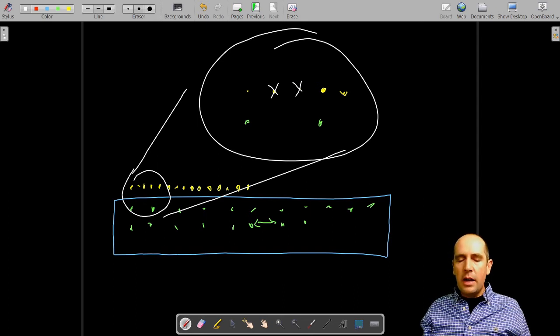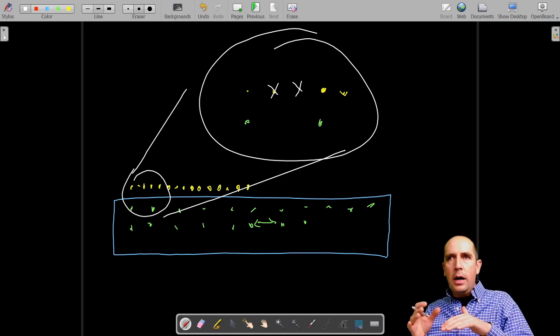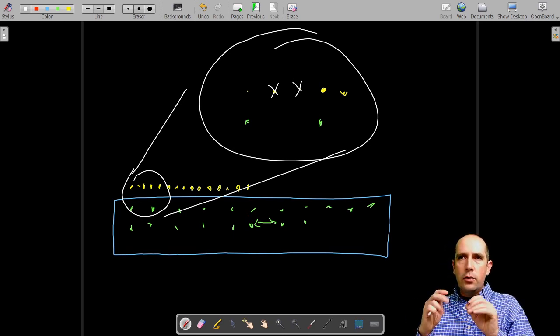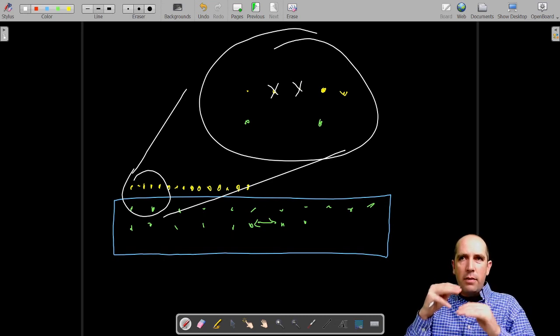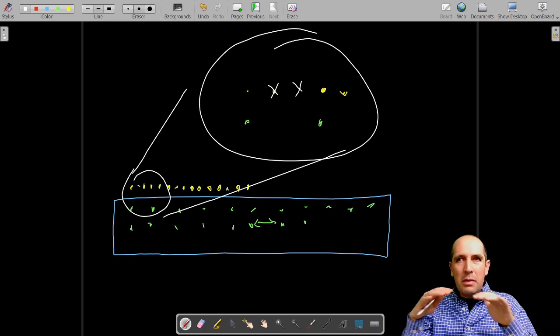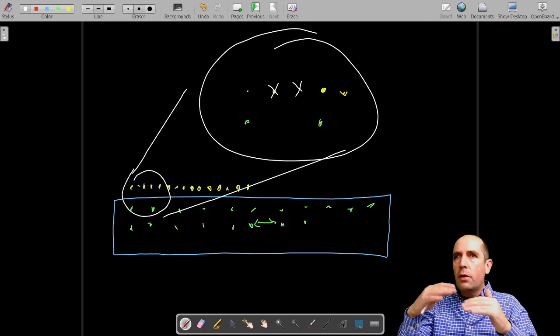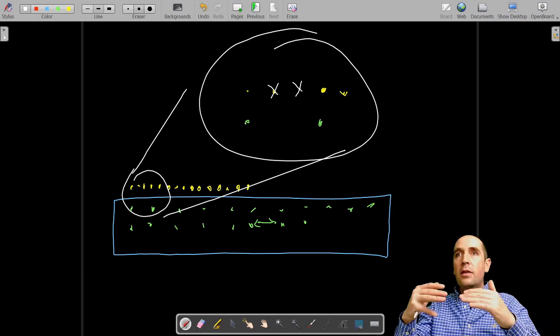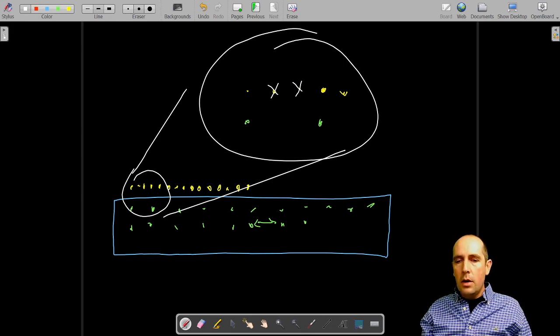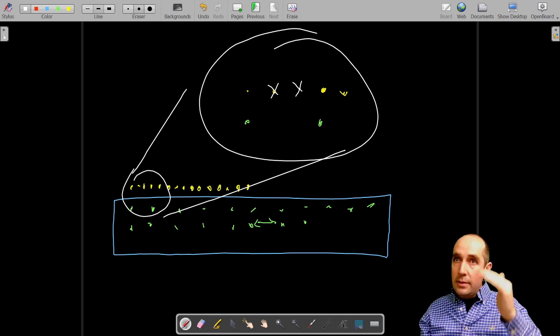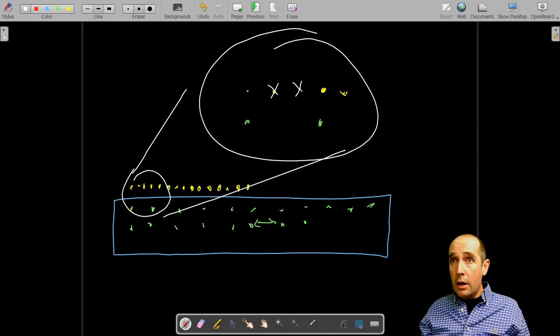Yet, a lot of development has been done recently in the field of growth of semiconductors, and some tricks have been done in order to either preserve the lattice, although you still have some stress in the crystal that grows, or vice versa, maybe not so much stress, although you will have a few layers which will not be very crystalline, they will be a bit disorganized. But eventually, after a few atomic layers, the new lattice constant more or less prevails, and the rest of the layer is a nice crystal. So all of these are possible.